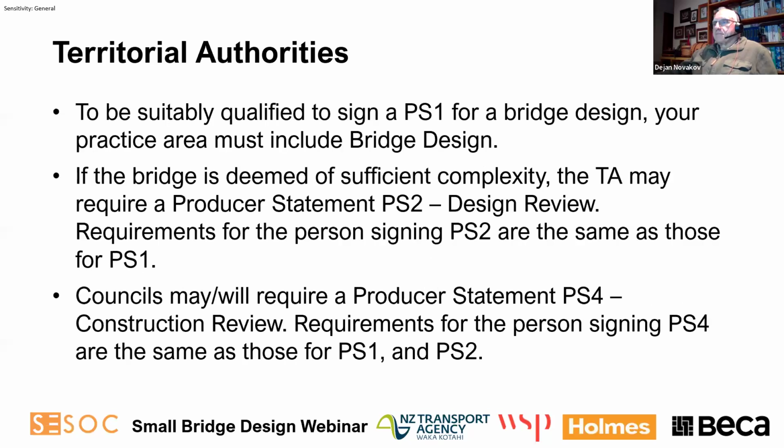Next slide, please. As I said, they'll be suitably qualified to sign PS1 or any of the other PSs, which will come later. Your practice area must include bridge engineering or bridge design. If the bridge is deemed sufficiently complex, the TA may require producer statement PS2 design review. That might be internal or external, it depends. And the same requirement as for PS1. Council also may or will require producer statement PS4 upon completion of the project. And again, the same requirement for the person signing it. Next slide, please, Jamil.